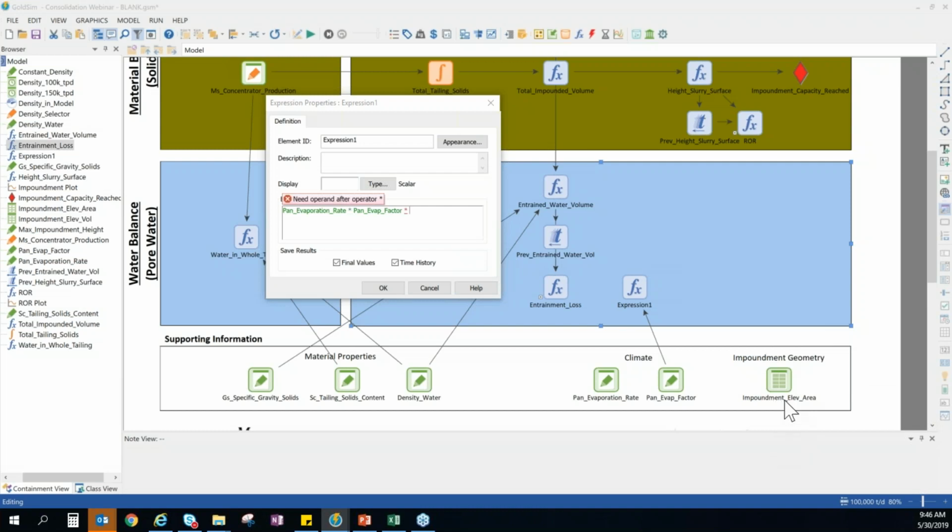As I mentioned during the PowerPoint presentation, we can do an elevation volume curve, and we can also develop an elevation area curve in terms of our stage storage. And that's what we've done here. The same analysis that was used to develop the stage storage curve that we used above for these volumetric calculations, we use that same analysis to develop an area curve, and that's what we're going to use here.